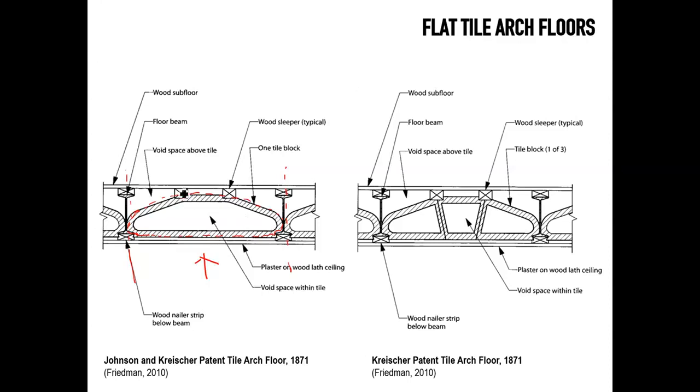Then it's also shaped to receive some sleepers or battens, as we say here in Australia, to then receive a wooden floor on top. And on the underside, this would act like a fireproof flooring system, because terracotta and clay tile is fireproof in the sense that it's not combustible, and it does protect steel. It prolongs its duration, its lasting capacity in case of fire. But you can see the problems of a system like this that is forcing the beams to be too close, or potentially putting too much strain on the tile itself, on the so-called arch tile.